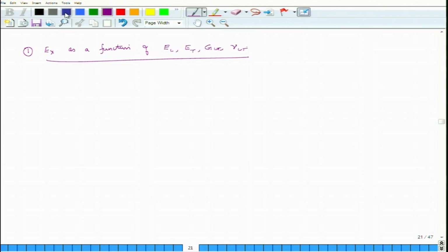So what we will do is we will analyze a lamina which is in a generally orthotropic case. So here we are applying sigma x, we are not applying any sigma y, and neither we are applying any shear stress.